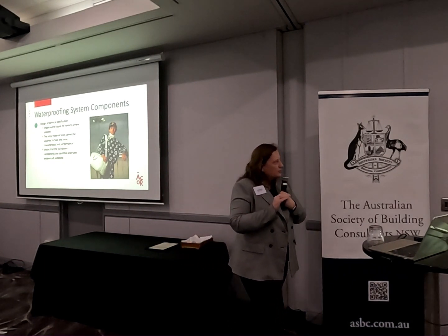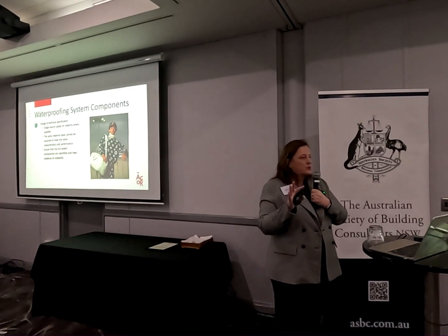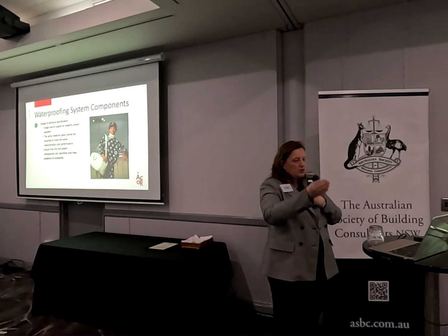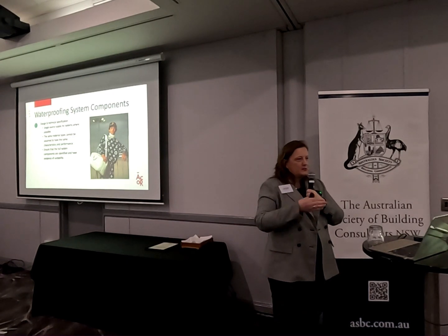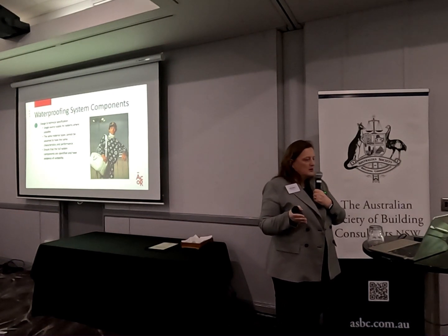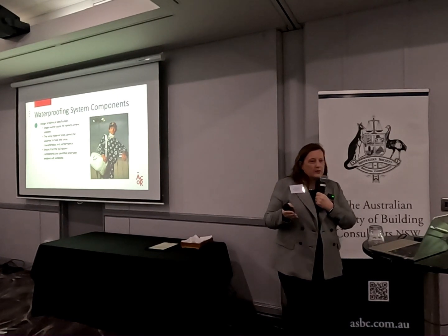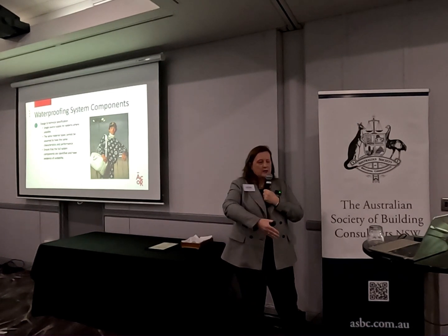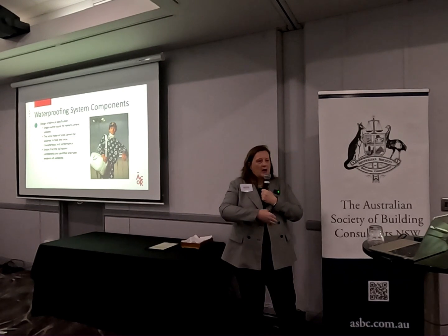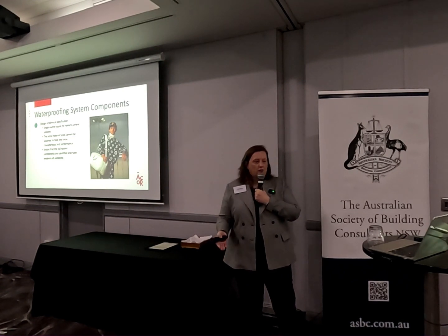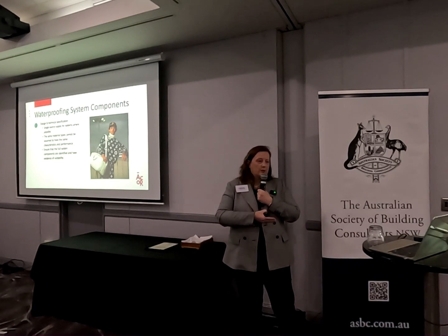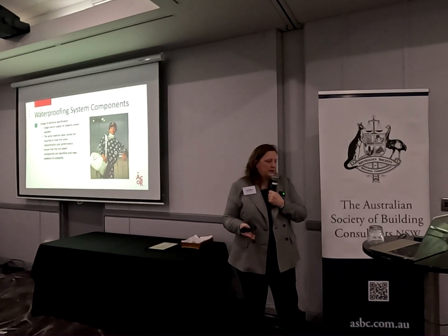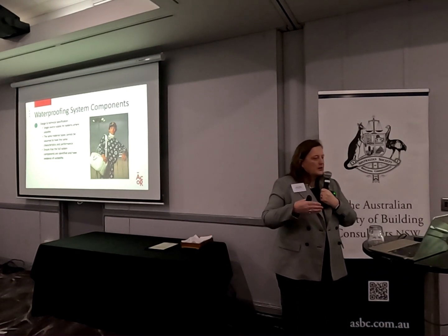So even though we've got the same materials, and we can say certain material properties will apply, just because this one's technology A and this one's technology A, it doesn't mean they're going to perform the same. It doesn't mean they're going to have exactly the same characteristics. So you can't assume that they're going to perform the same. You need to actually go down and look at the evidence for that particular product. What is the performance? What is the history? Are there other projects? How well does the manufacturer know this product and how to apply it and how to problem solve? How well are they going to support you if something doesn't necessarily go to plan? You need to go to that extra level.